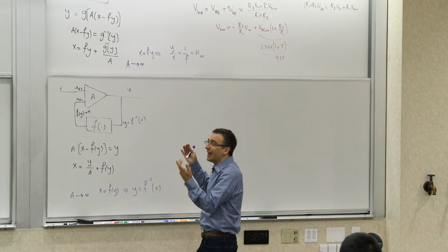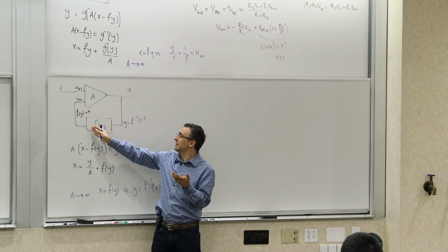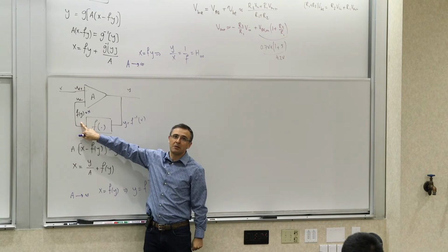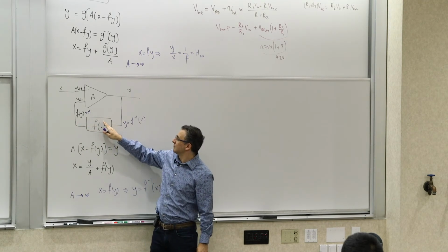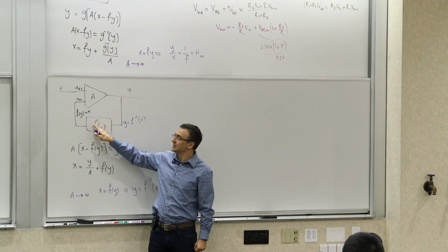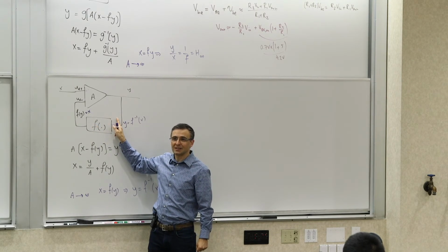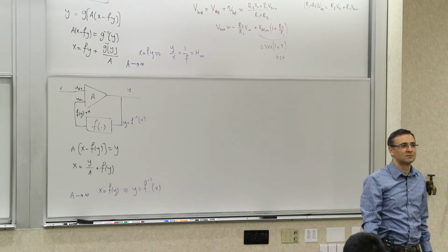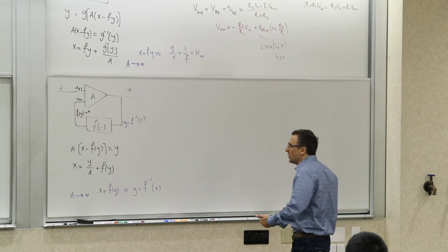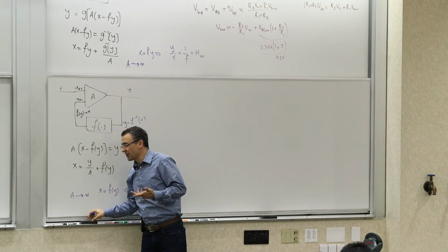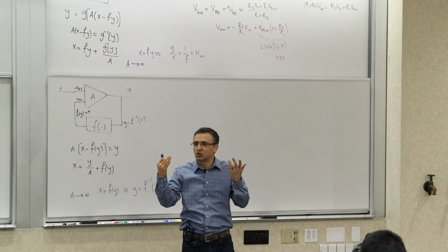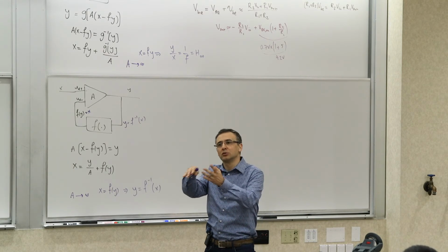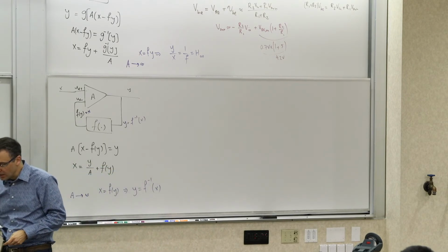If you have a PLL and you have a frequency divider here, it becomes a frequency multiplier. Because if the frequency here is 1 megahertz and your division ratio is, let's say, 8, then this has to be 8 megahertz, so that when it gets divided, it produces 1 megahertz. So when you think about it this way, it's not that magical. It's what it should do, it's the action of the feedback. It forces it to go to the place where this happens.